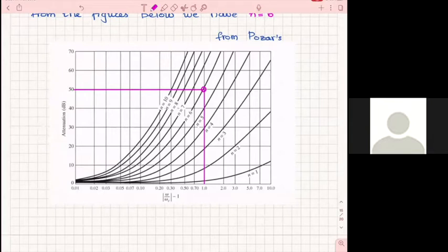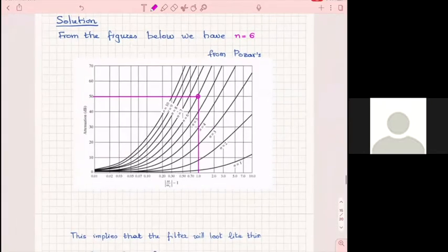And I would always go for the simplest realization, because as you can see, things can become very complex as you try to implement it. So even when you don't have any specific requirement when it comes to equal ripple or maximally flat, you always go for the equal ripple, because for the same rejection, you will always have fewer sections.